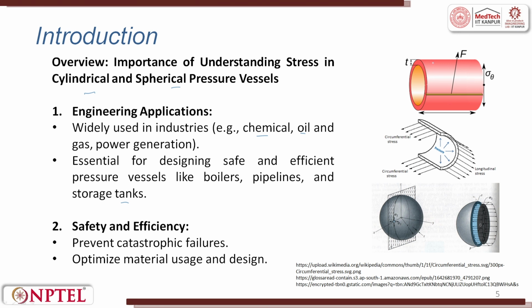If you take a cylinder, as I already discussed, t is the thickness, the stress acting along the direction perpendicular to the axis, and then you will also have theta. So the stresses are going to be circumferential stress, and the one along the axis is called longitudinal stress. When you fill a cylinder with liquid or with air, you are pressurizing it. This pressure will lead to circumferential stress and longitudinal stress.